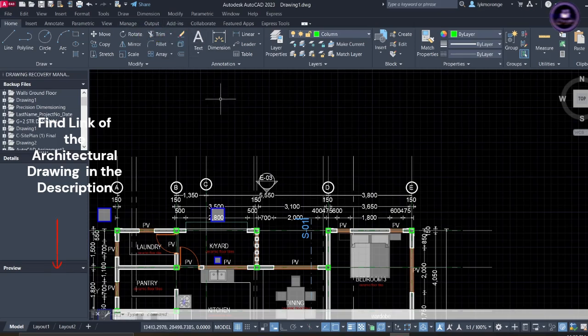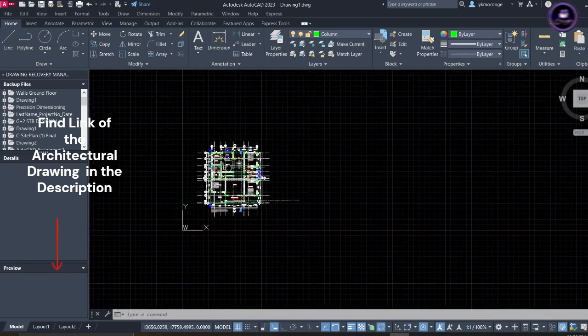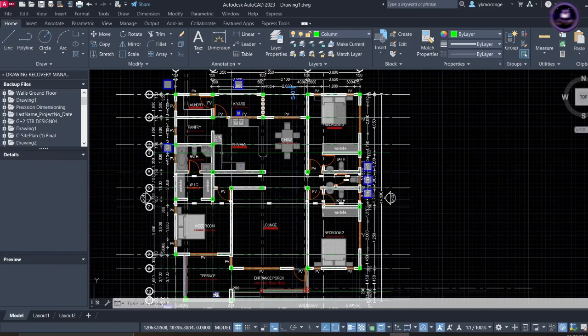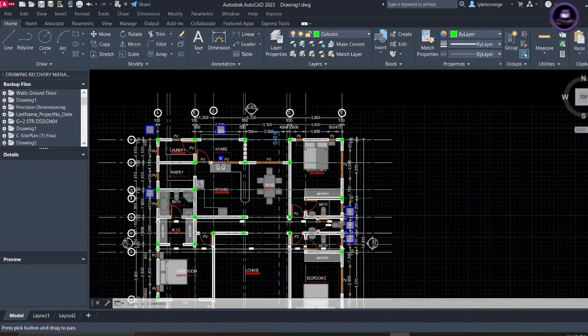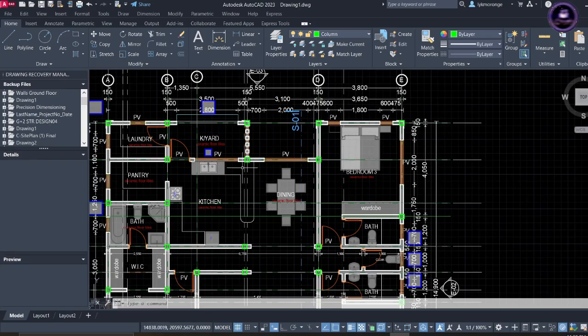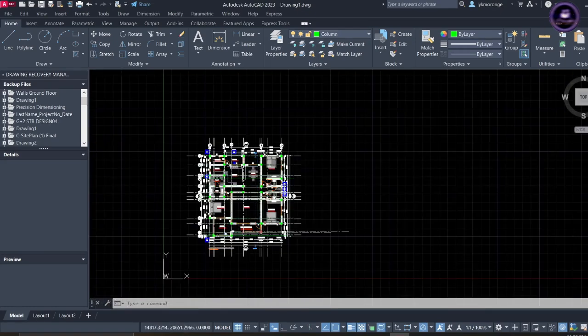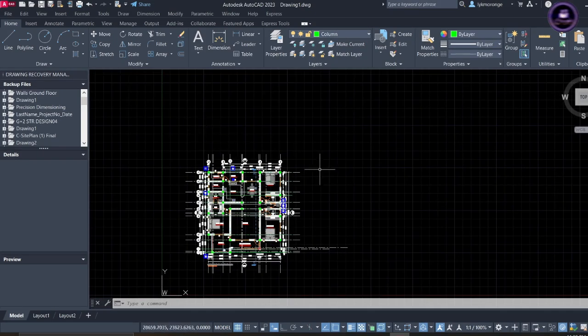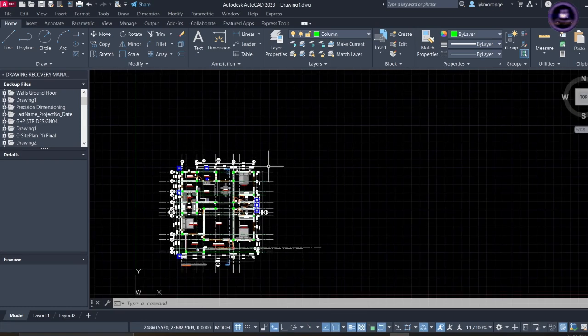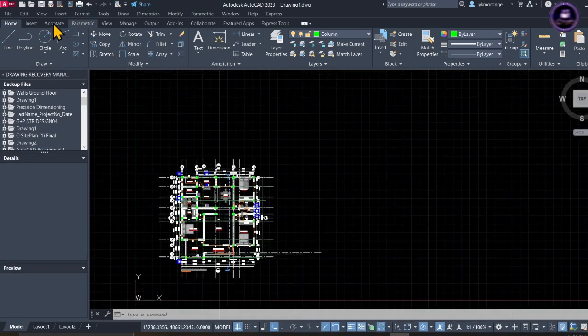If you are tasked to just prepare a general arrangement drawing, which will subsequently proceed to ProtaStructure for design of your building, the first thing you do is import the file you've been given into AutoCAD.